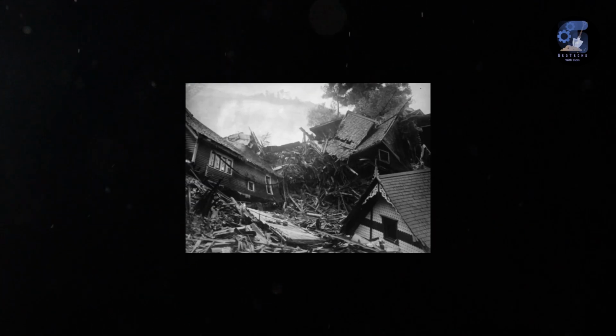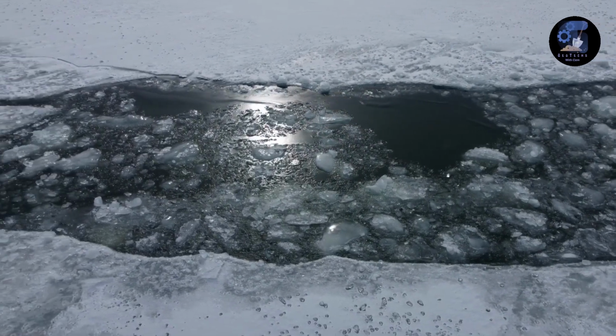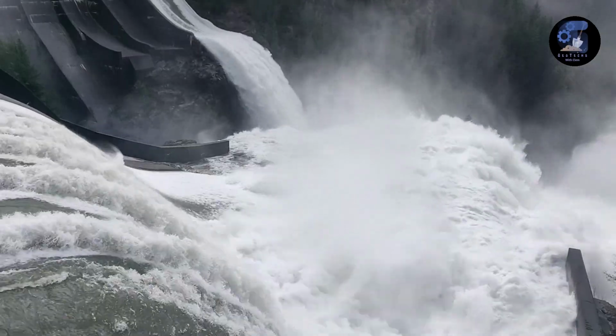In mid-January 1910, a warm period combined with rain caused a snowmelt that filled the reservoir behind the Austin Dam within 3 days and the activation of the spillway for the first time. On the next day, the dam slid downstream on its foundation, deflecting 18 inches at the toe and 31 inches at the crest and cracking in several places. Though divided, the dam remained anchored to its foundation rock. However, the foundation was poorly constructed and the rock layers slid over each other.